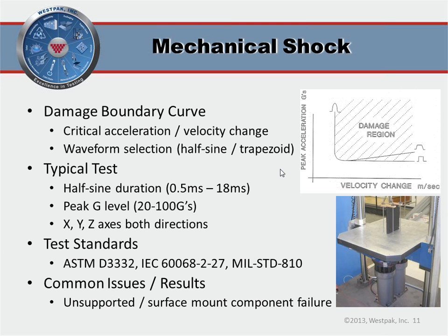The bottom picture shows a typical test setup where a product is fixtured. In this case, our dear old laptop is fixtured to the top of a typical shock test machine. This is referred to as a drop shock because the table itself falls and impacts the programmers to produce a shock pulse. So the common results that we're looking for are, like I said, critical velocity change, critical acceleration, and we normally continue or step the inputs up in each orientation until failure occurs.